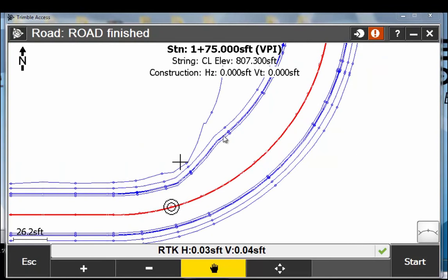I haven't done it in a while, worked with survey guys, but I remember with previous times we've done this export of road with the frequency you're talking about, how it shows every station that we sample a corridor at. Is there a way, instead of making a copy of your corridor or something and changing that frequency, to get that as an output to something that they can back off of if they don't want all those? So you want to be able to dial down the frequency of your corridor once it comes in here.